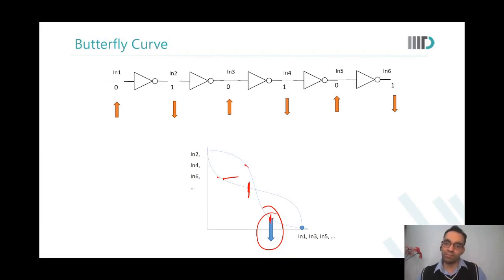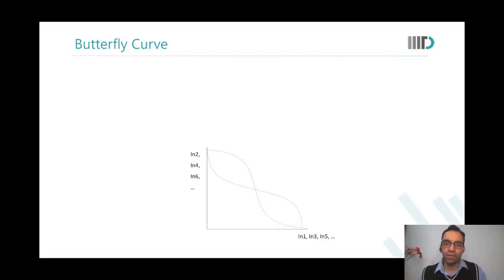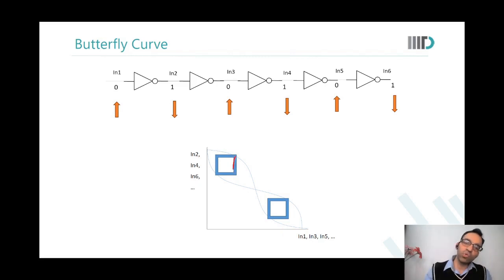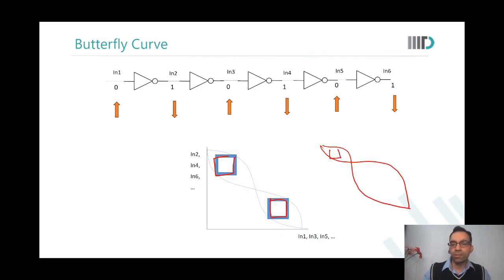So what is that unique case which we would call the noise margin? That unique case would appear something like this. I put some noise there, and here. Now this is the largest square that I can fit into these lobes. If there are two asymmetrical lobes, then the smaller square is the noise margin.